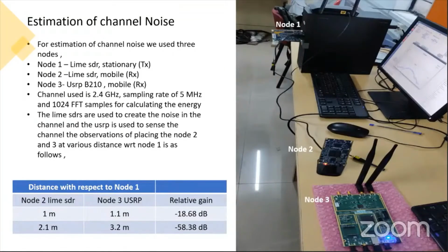In order to determine that, we again had another experimental setup where we had a transmission mode, a noise creating mode, and again a receiver mode. And we measured 2 ED thresholds. One was in high noise areas, or a channel which is prone to high noise, and the other in a channel which has relatively less noise.